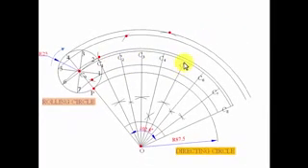Now we have C5. We've got to make sure that this arc passing through 5 is intersected. With C5 as center, you again put an arc over here. So this is going to be P5. C6 as center, and this is the arc through 6. With C6 as center, you put an arc over here. That's point P6. Fine. So this is the arc through 7, and with C7 as the center, you make an arc over here. This is P7, and finally we take C8 as the center. The arc is just going to touch this, and this is going to be point P8.